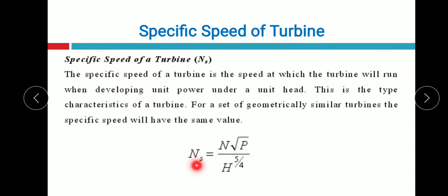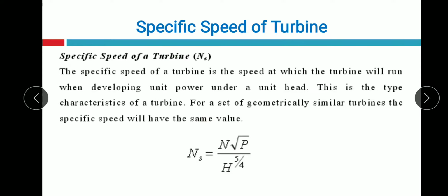Then you have to check this Ns value against the table I gave in the first video, the specific speed range. Based on the specific speed range, if it is 10 to 30, then it comes under impulse turbine, like that. If it is 20, it comes under impulse turbine. Ranges we have given in the first table. Just go through that and remember this formula. Those two are very important, and these types of questions are very important from the point of view of competitive examinations, the external examination as well as the internal examination. Please go through it, the very important formula.